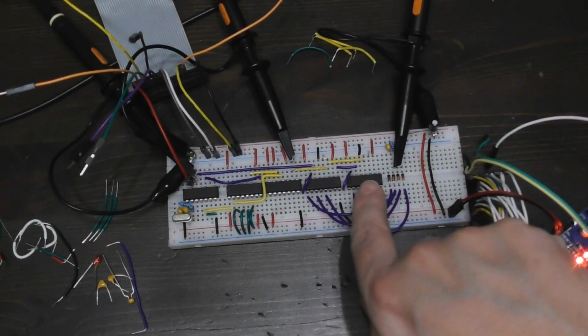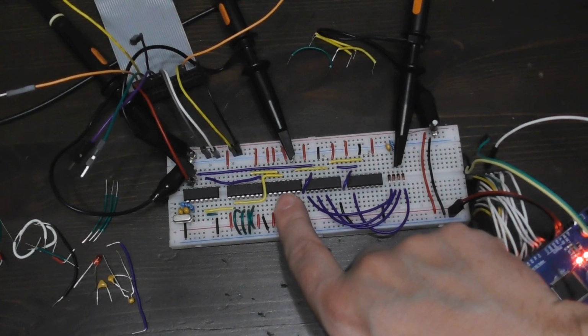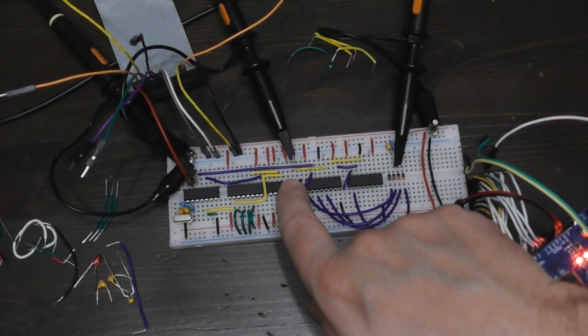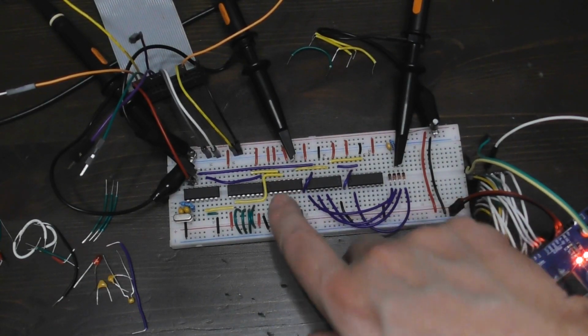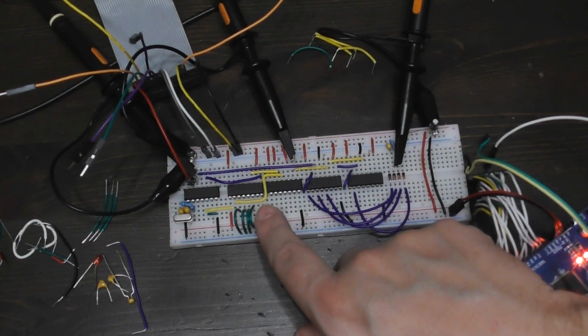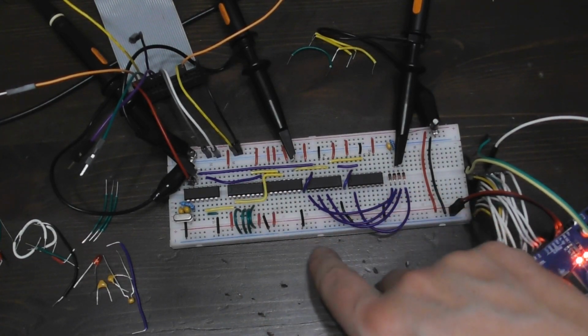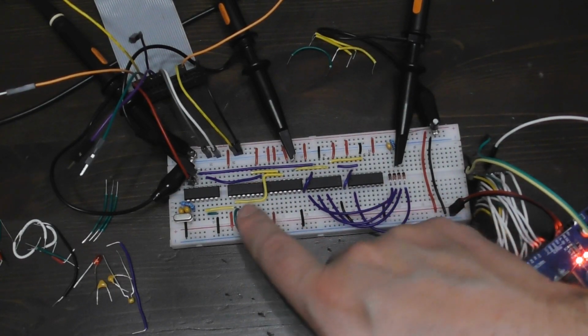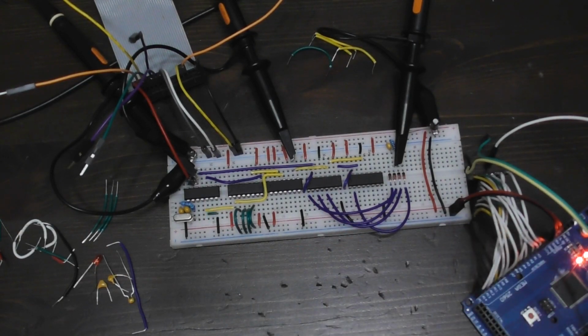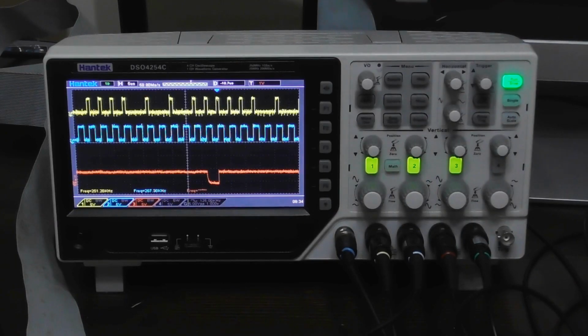Now I moved the shift registers along and I've inserted a dual D flip-flop. That's a 74AHCT74 I think. And I'm using the top half of it as a D flip-flop to delay the clock that's coming out of this counter chip here. So it's delaying the output from this counter until the next tick from the 4 MHz oscillator, which is maybe a more consistent and a bit more substantial way of delaying than simply chucking a load more inverters in.